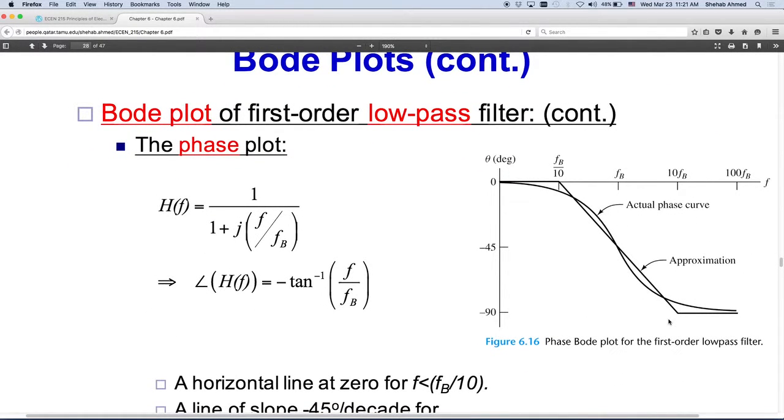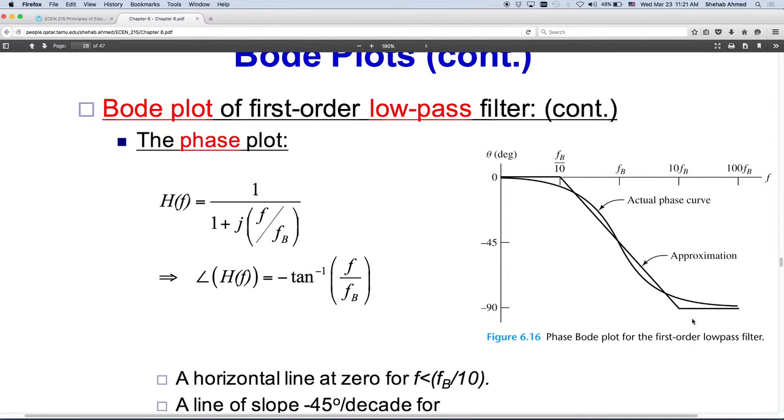But we know capacitors, what do they do? If it's purely a capacitive circuit, all it can do is change the phase by 90 degrees. Remember, in a pure capacitive circuit, what was the angle between voltage and current? 90 degrees, right? Cannot be more. It's always fixed for a pure capacitive circuit. So the most that it can do is phase shift by 90 degrees. That's why these 90s and 180s will be important, because anytime we have two capacitors in the circuit, we will not. We will only do first order. But this is where the 90 degrees comes from.